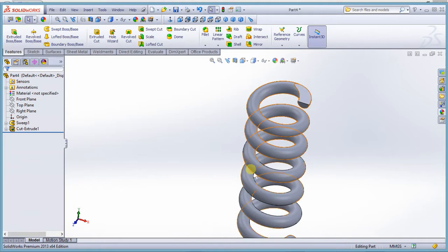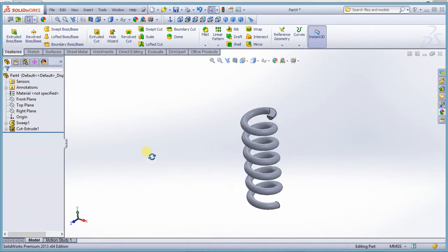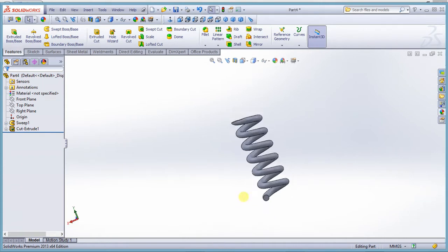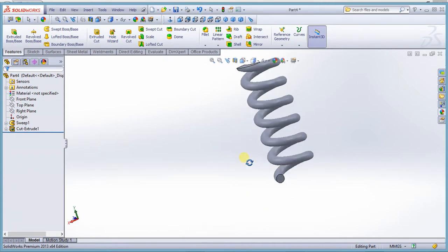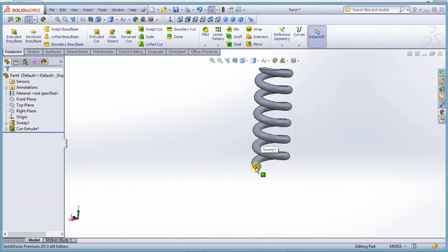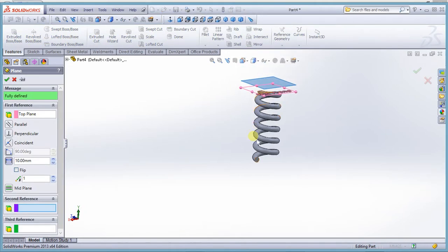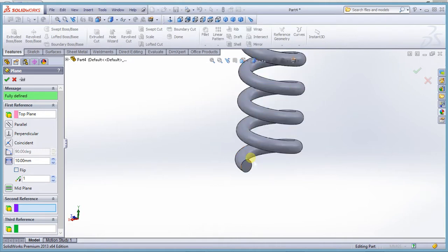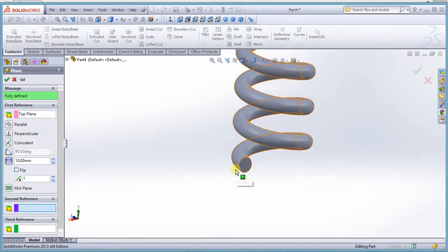We are going to do the same to the down part. You can rotate it to have this face. Now we are going to add a plane that will enable us to cut this other down part. You select top plane, just select it, don't sketch. Come to reference, under feature, reference geometry, add a plane. Where to place that plane? Don't click OK here. Come to this surface.